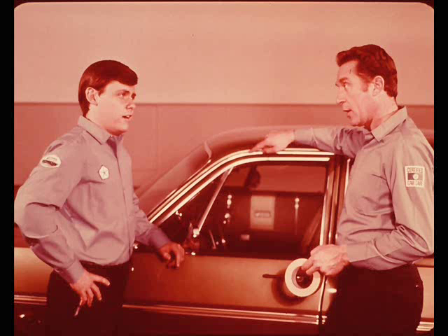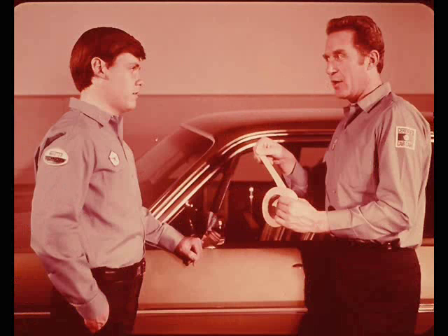Once again, you start with the obvious. Be suspicious of a molding that is loose, raised, or out of place. You can either correct it right then or temporarily cover it with masking tape before you make further tests. Even if you fix obvious things like loose moldings or open body joints, trying to find the cause of turbulence noise in the shop is largely guesswork. However, since outside testing takes time, it's a good idea to correct the possible troublemakers in the shop.